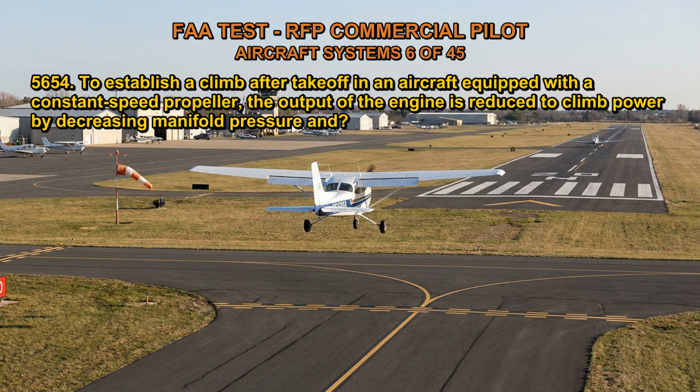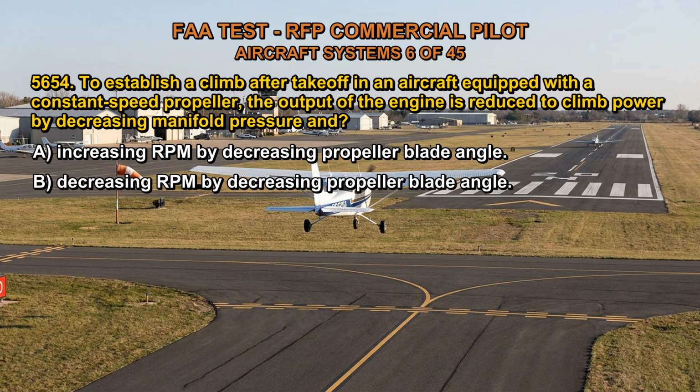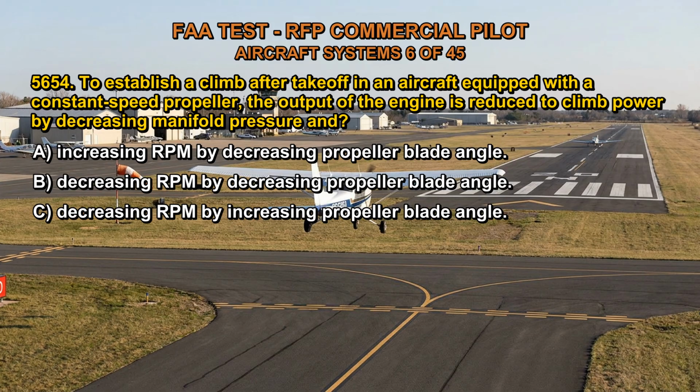5654. To establish a climb after takeoff in an aircraft equipped with a constant speed propeller, the output of the engine is reduced to climb power by decreasing manifold pressure and A. Increasing RPM by decreasing propeller blade angle. B. Decreasing RPM by decreasing propeller blade angle. C. Decreasing RPM by increasing propeller blade angle.